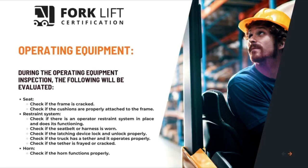Operating equipment. During the operating equipment inspection, the following will be evaluated. Seat. Check if the frame is cracked. Check if the cushions are properly attached to the frame. Restraint system. Check if there is an operator restraint system in place and if it is functioning. Check if the seat belt or harness is worn. Check if the latching device locks and unlocks properly. Check if the truck has a tether and it operates properly. Check if the tether is frayed or cracked.